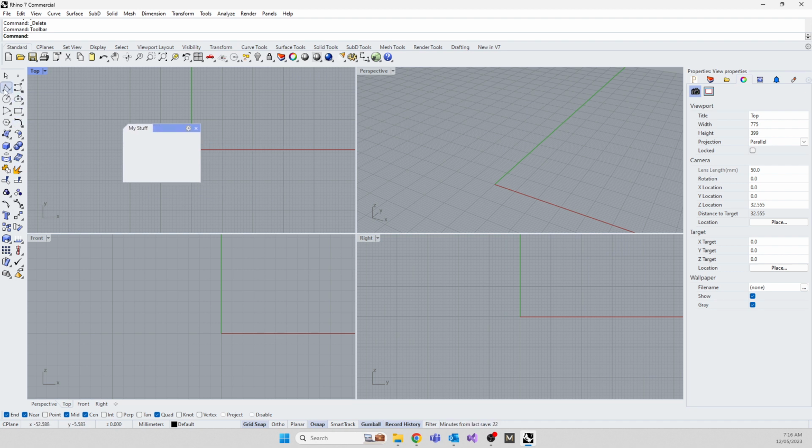So let's say I use polyline a lot, and I want polyline in my toolbar. So hover over polyline. Press your control key, and you'll see that you can copy this. If you hold your shift key, you can move it or edit it. Remembering that you've got two words up there. The left mouse will do move, the right mouse button will do edit. Same when I hold control, I can copy it, or right click, I can link it. So I want to copy this one to here. Okay, so now I've got a copy of this one.